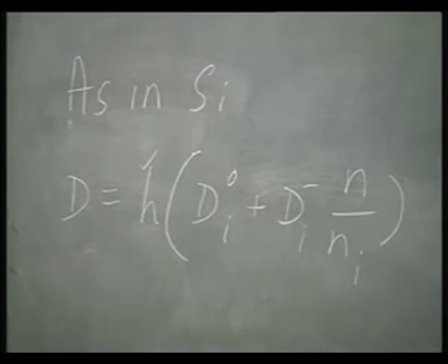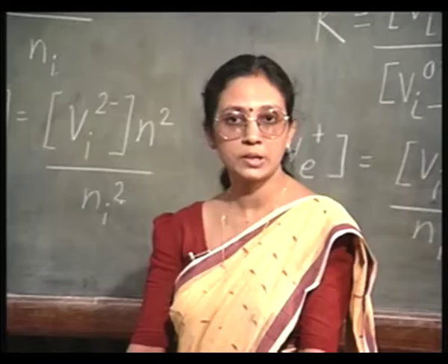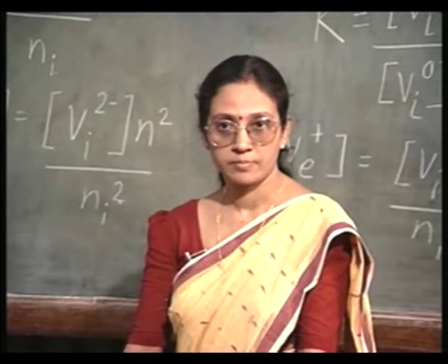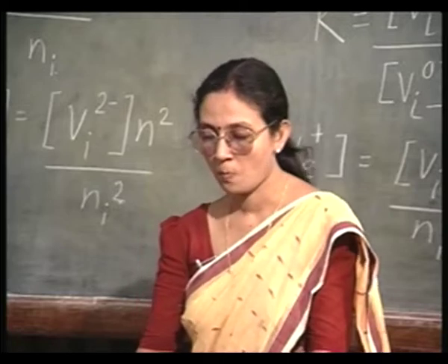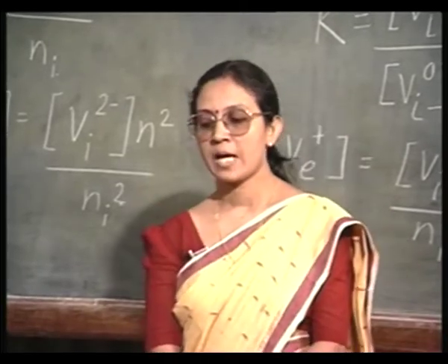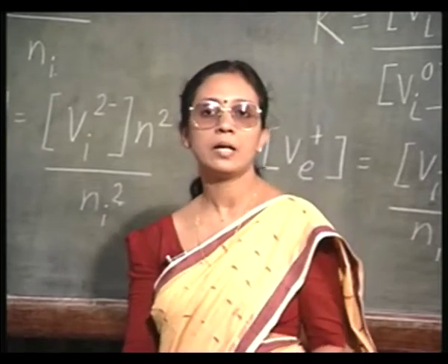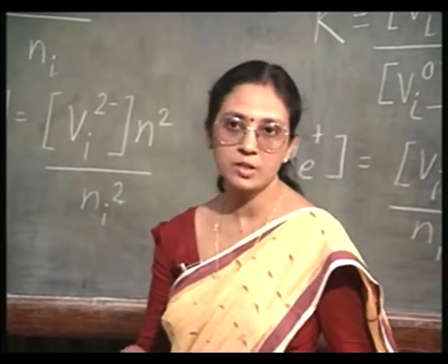The first term is independent of the dopant concentration and the second term is proportional to the dopant concentration. That is, this is determined by the interaction of arsenic with the singly negatively charged vacancies. This can be fitted by a numerical solution.